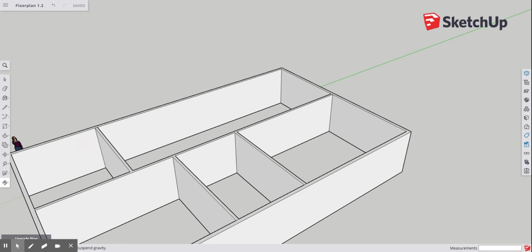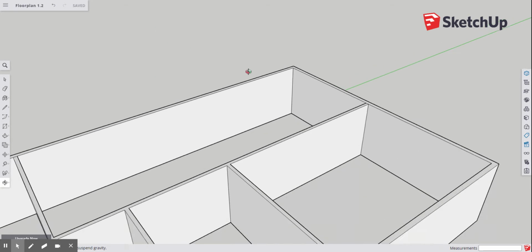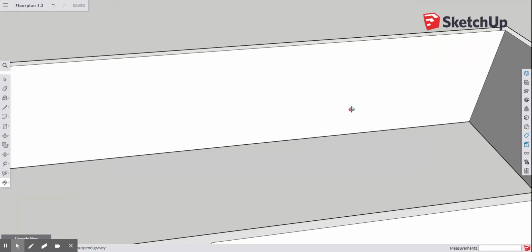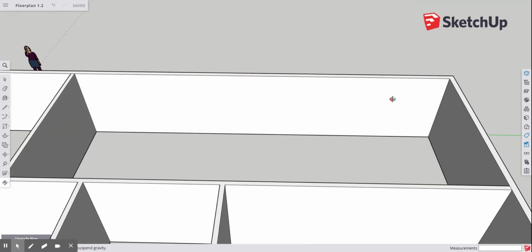What is the same is our door sizes and kind of the window heights. So what we want to do is create little openings, like when you're building a house, you want to create an opening so you could place a door slab in that door opening. We want to start from the inside. So when I'm measuring how far my door is from the wall, I'm going to be referencing the interior walls throughout this video.